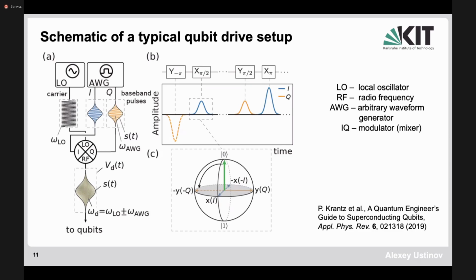And once you have these intermediate frequencies applied to the local oscillator continuous signal, this local oscillator cuts the profile such that it upconverts the two signals, generating signals at the frequency of the local oscillator plus and minus the frequency of the arbitrary waveform signal. And by choosing particular I and Q phases, one can do the so-called single sideband conversion.